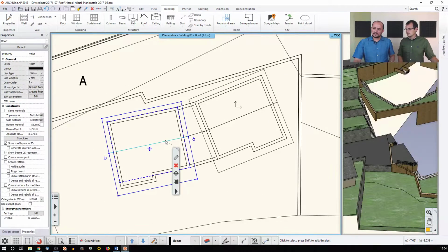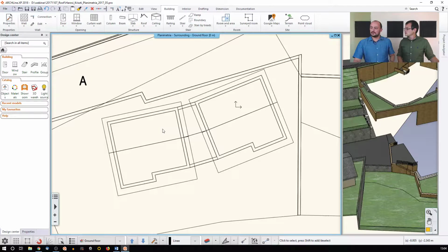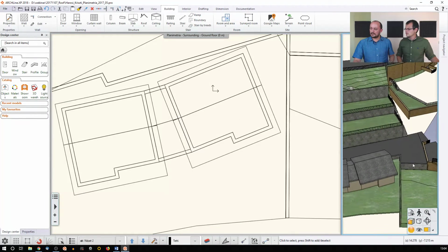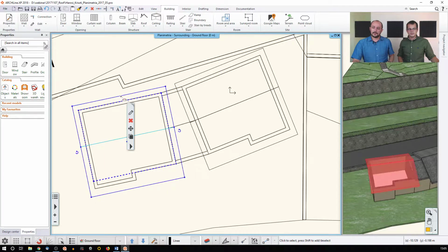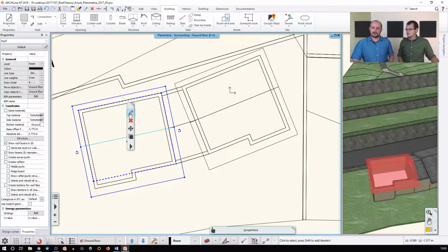And then when I select the roof, by default the roof behaves just as on other building parts. It is represented on the floor where you create it. So when you draft the roof, you will see the contour at least, or depending on the settings, you can see the framing as well. I will go deeper into that soon. But there are two specific things considering the roofs.